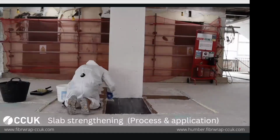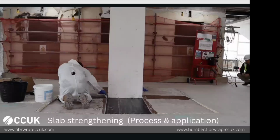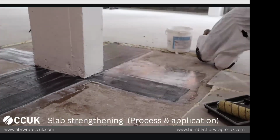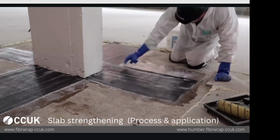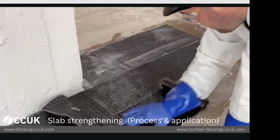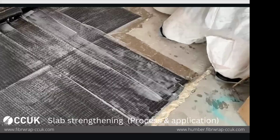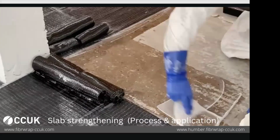Then provide another coat of epoxy, another layer of carbon fiber, and that's how they build up the number of layers. Now, because this is an application on top of the slab, you're not restricted in how many layers you can apply in one shift or one day. But if it was a vertical application or on the underside of a slab, then you can only apply 3 layers in one day. After that, you have to wait for it to initially set and cure, and then you can apply further layers. The initial setting time is 4 to 6 hours, and it will be 100% cured in 72 hours in ambient condition. So you can reload your structure back to its new capacity in 3 days. So that's how they do the application.